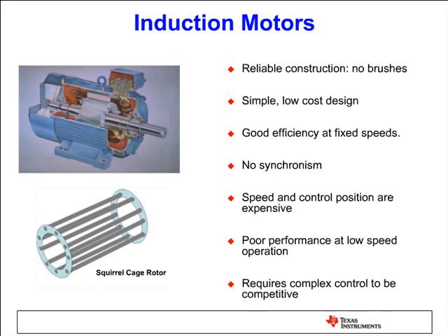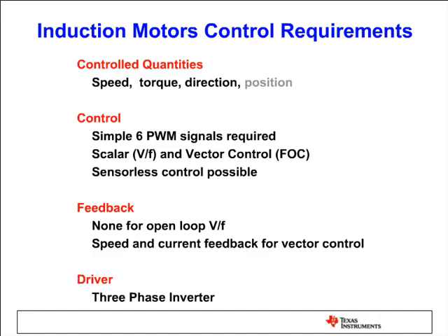The disadvantage of the induction motor is the control of induction motor is not straightforward. It's quite complicated. Again, we need mathematically intensive algorithms to control. Using induction control, it's very hard to control the position, almost impossible. Instead, we control speed and torque. For speed control and torque control applications, induction motor is a very robust and cheap and good candidate.